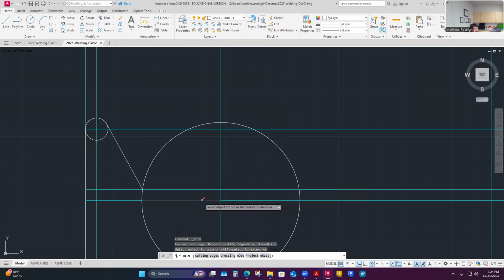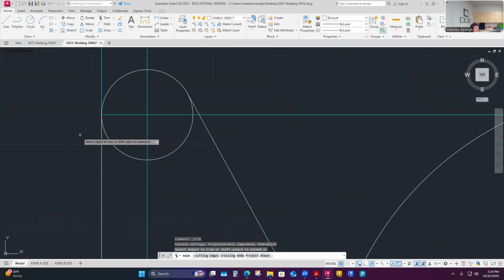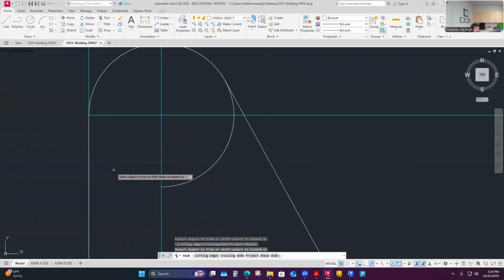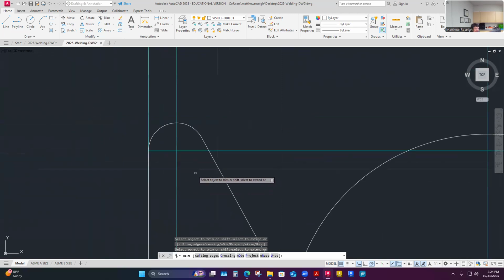And so when you have a lot of layers up, even to cut this, like watch, I'll come into this and really want to trim this, but I also got to trim this little section right here, right? So this is one way to do it. Just zoom in on the geometry and then just be like, yep, that's trimming. Come over here. This is going to trim. And then I got to zoom in here, make sure this is going to trim, right? I could totally do that. That's all one command. If I hit enter, all that is one command's worth of trim.